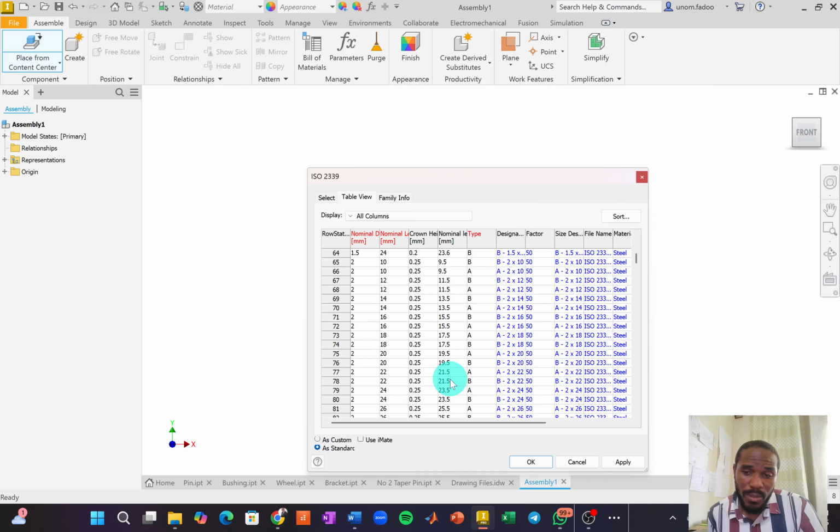All right, so the Content Center is where you can insert parts of your assemblies that are standardized products, okay, that are in the market, from fasteners, which includes bolts, nuts, pins, different kinds of pins, groove pins, cylindrical pins, to rivets, to washers, to shaft parts, to tube and pipe fittings, okay. You can do all of those. So that's the Content Center.